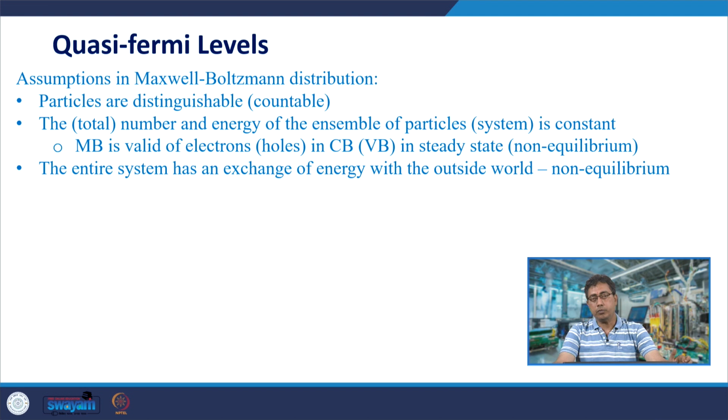In case there is steady state and there is no equilibrium, you cannot estimate the electron and hole concentration using the idea of Fermi level, because, due to the external energy exchange, the hole and electron concentrations are now not at the equilibrium value.